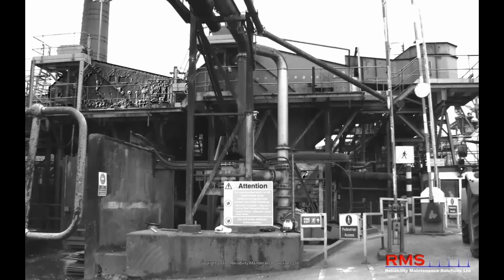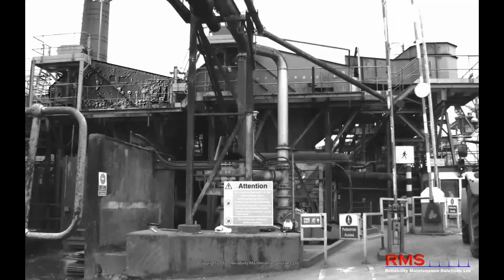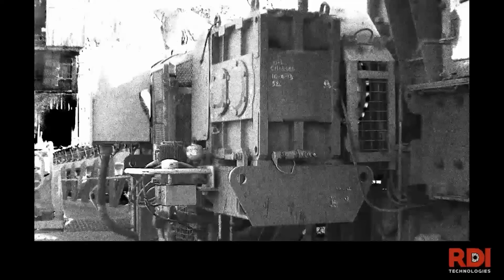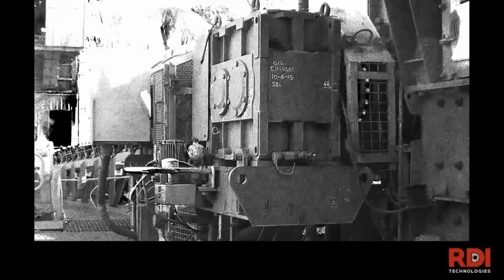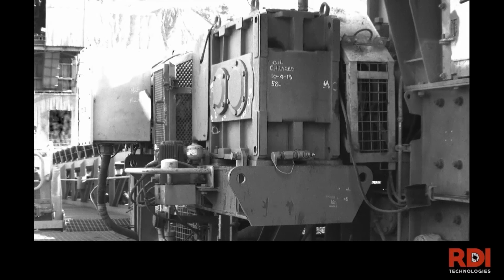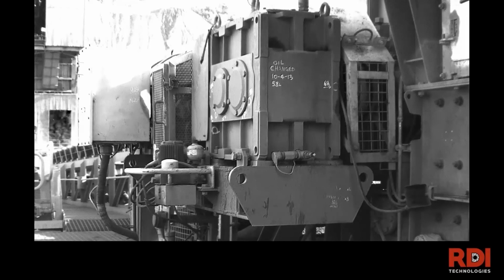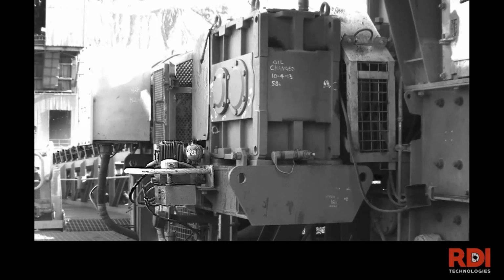So again, what I wanted to do is just demonstrate the ability to show different frequencies, because it's a very important part of this, just to set up the background. Again, we're showing this overall motion of this motor here, and then we can filter for individual frequencies, like the 2 hertz of the output of the gearbox, or the 25 hertz for the motor, or something in the background, like the 4 hertz on this conveyor that's bouncing in the background, which actually ended up being the real issue here.